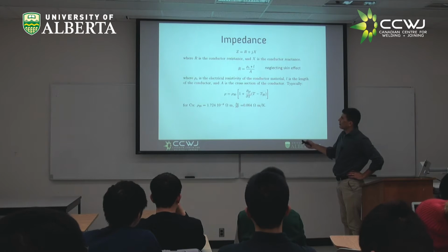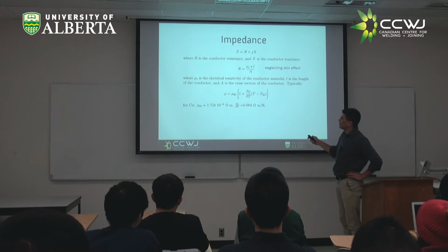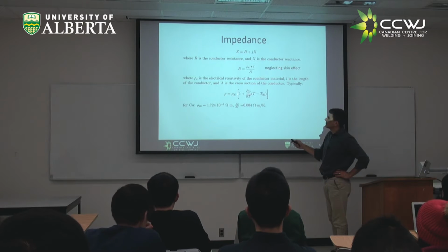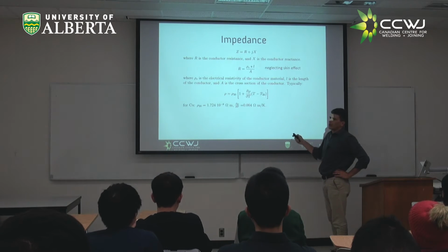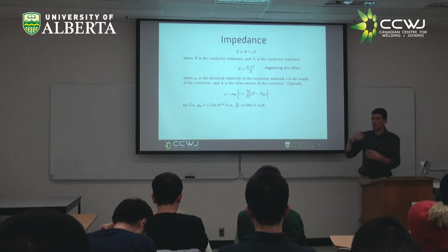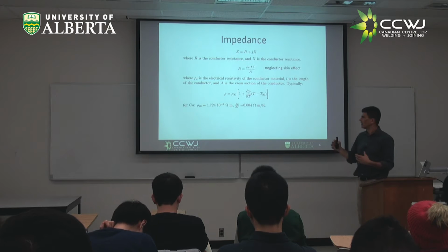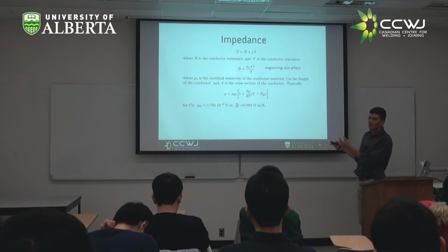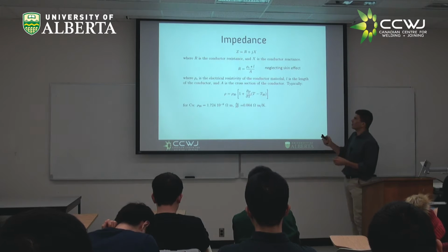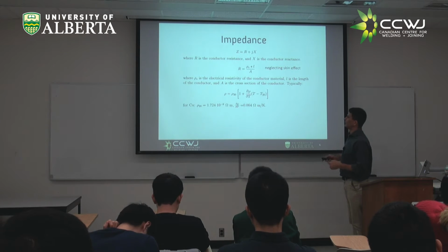Resistivity, which is a material property, is often captured with a formula like this that says resistivity at 20 degrees times some sort of variation with temperature, right? Typically, with higher temperatures, you have a higher resistivity, right? And this is for copper. And I put copper here because our leads are made out of copper, and that's what we're talking about. I have these values here.